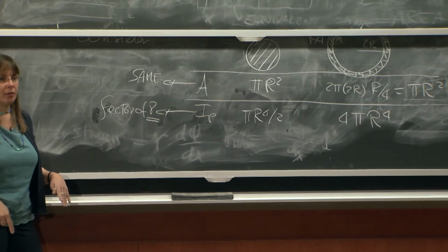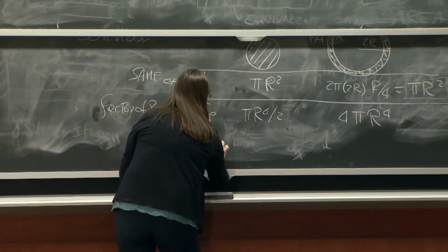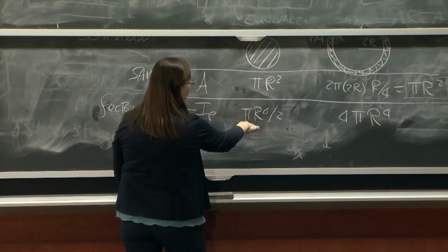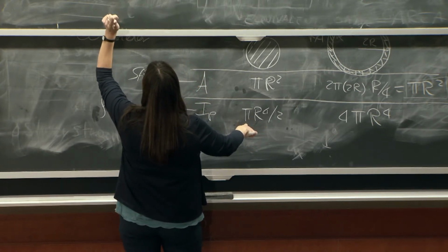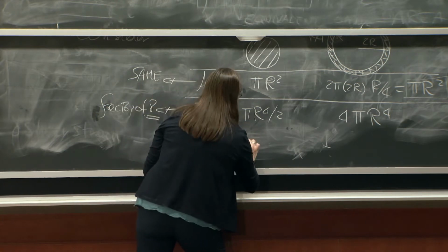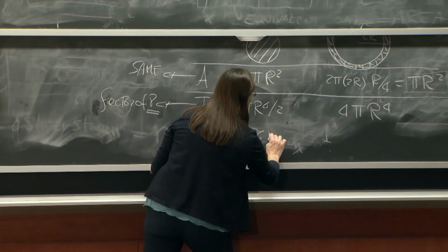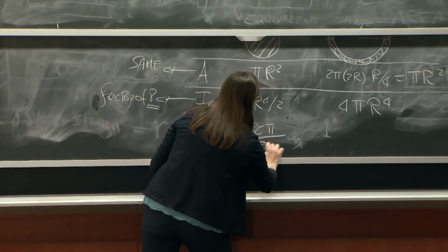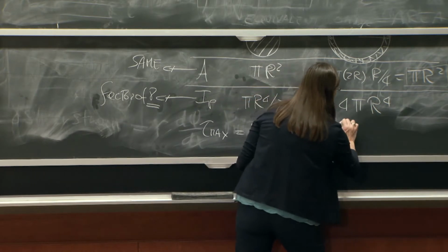You see? And my stress, if I calculate my stress, tau max, when I multiply the torque by the radius, is going to be equal to the torque times the radius times this. So it's going to be torque times 2 divided by pi r cubed. And this one here is going to be torque.